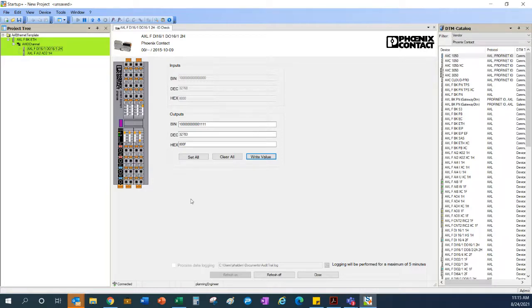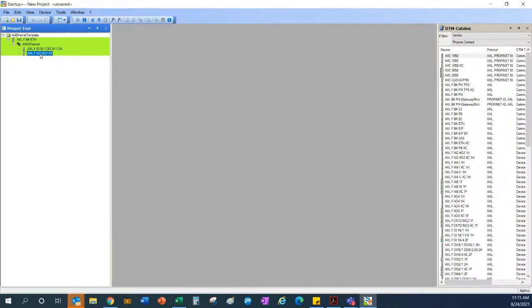So this allows the guy building the panel to actually connect up with the software and just physically test the connections. Oh, the output's on. Do I get the reaction I expect to get? Is everything wired correctly down the road? Now, this is great for the digital modules. We can even go as far as the analog modules. We can do the same thing.